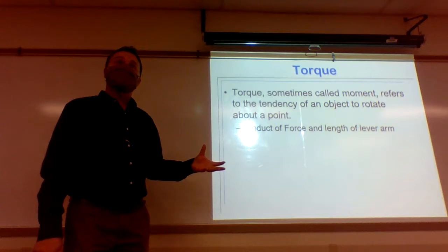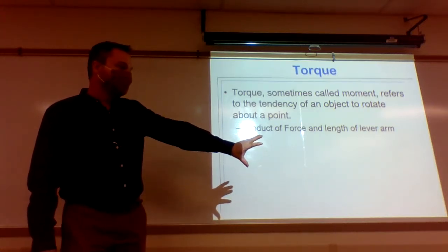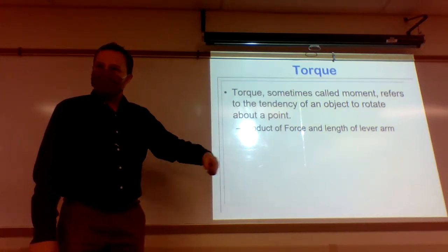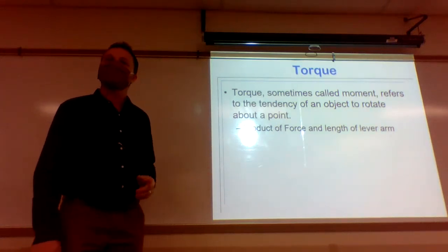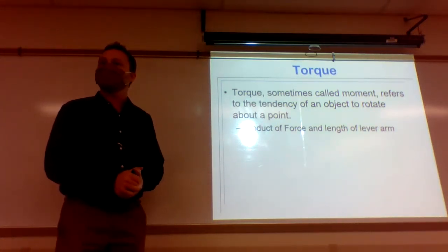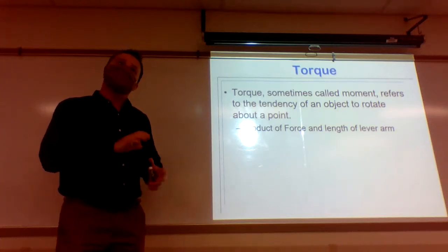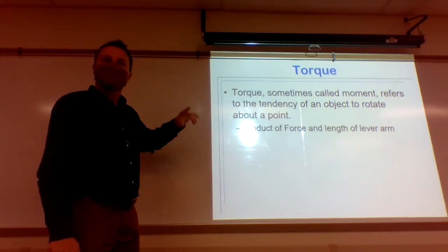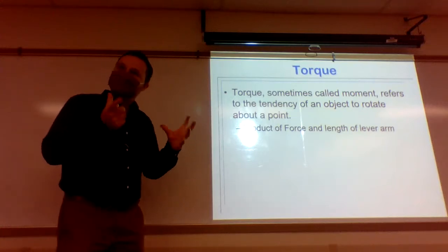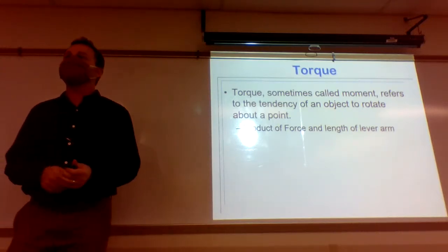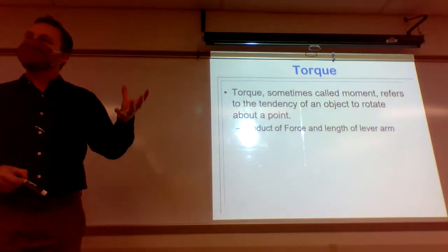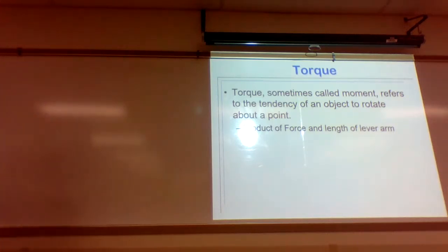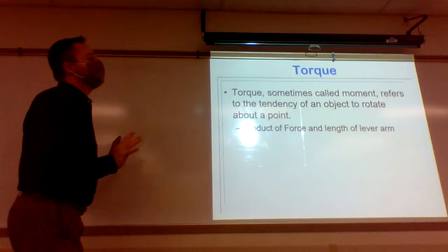To get AC electricity that comes out of our wall, that electricity needs to go back and forth 60 times every second, meaning my generator needs to be turning at roughly 60 times per second, or structured in such a way that it generates 60 hertz electricity. So how do I get that exact speed? Well, if the turbine in my power plant spins at a different speed, can I use it? Yes. I just have to hook up a certain set of gearing ratios, a transmission that adjusts the speed of the output to turn the generator at the right speed, so I get 60 hertz coming out of the wall.